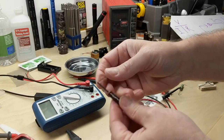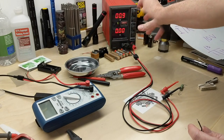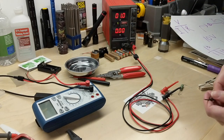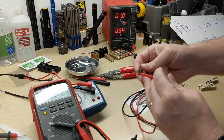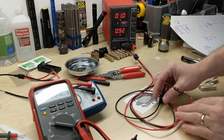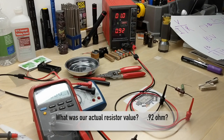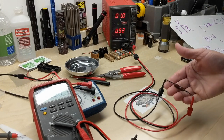So now with our 1 ohm load, now we have our power supply on 1 volt. Alright, so now I'm going to put the load across. And we see how we're very, very close to being 1 amp. We got 1 volt, 1 ohm, and 1 amp.